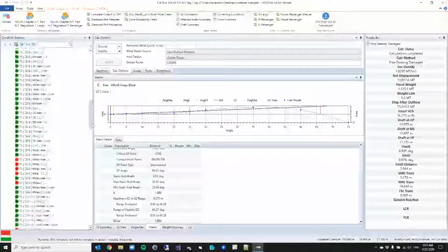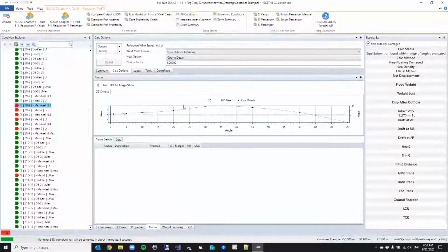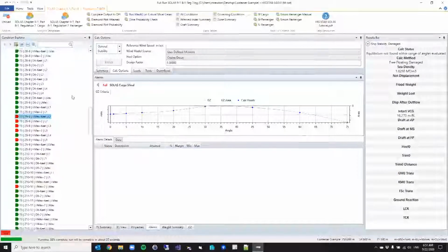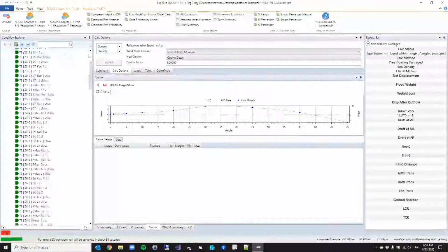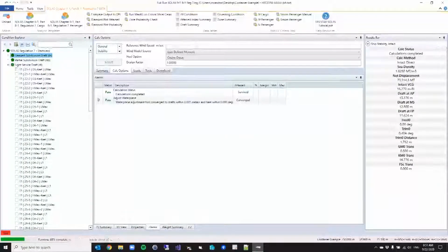You'll notice as it's going, it's running into some cases where it can't even calculate a damage stability for certain damage cases, which isn't a failure in this case, as it's a probabilistic approach. It just means that it's not getting any contribution from this damage case. You can see in some cases it's failing calculations. But as it's gone through, it's done my first 2 drafts. It looks like I'm ready on my third here, so it's going through and calculating things quite quickly.